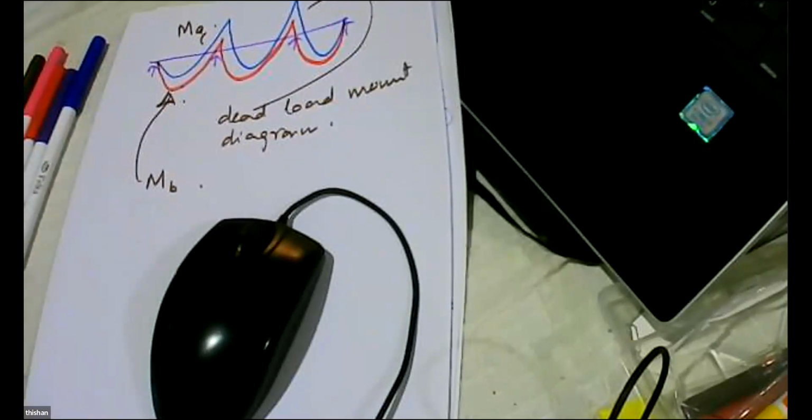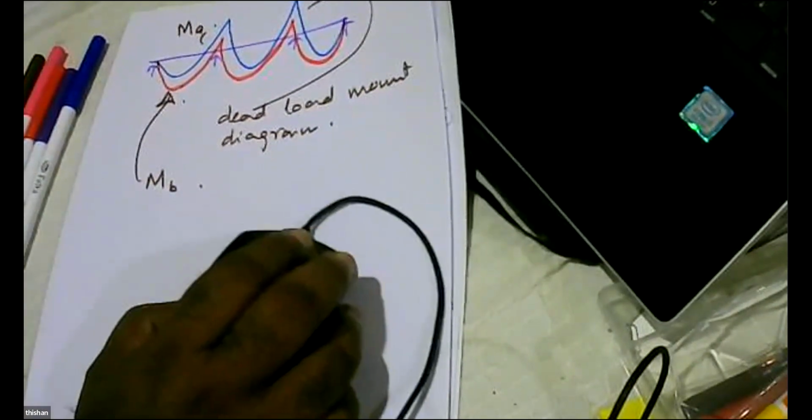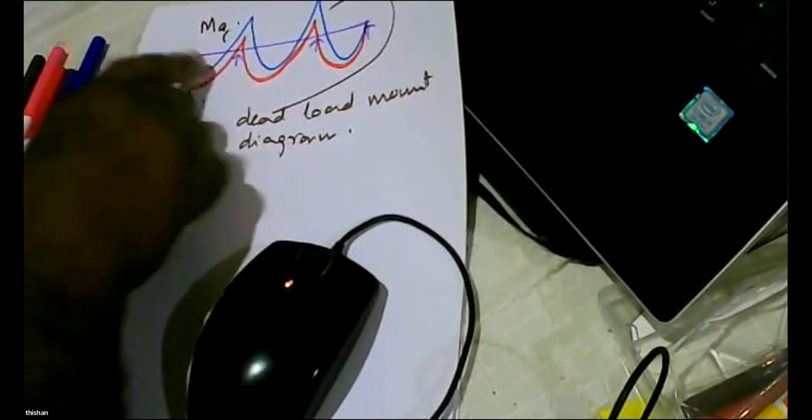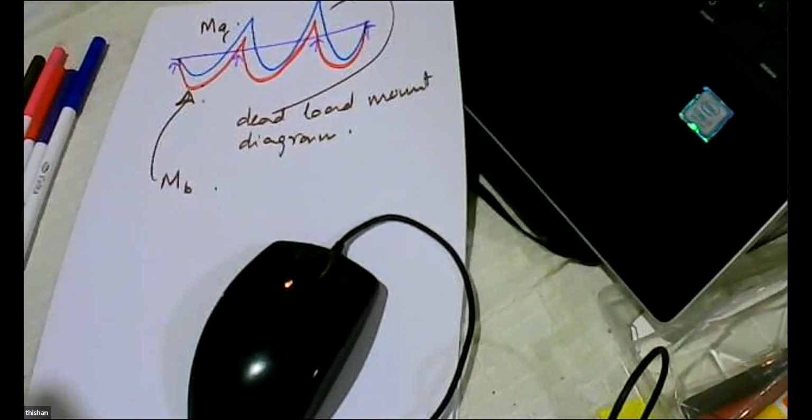And the bending moment diagram that you used should have been an envelope, not a diagram. Because you did not use an envelope, all your calculations are wrong because the moment range is wrong. Because we are using the lower boundary to calculate MD and the upper boundary to calculate MA, you are actually adopting a proper moment range.